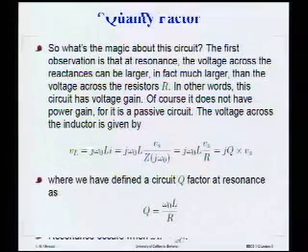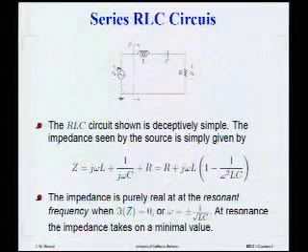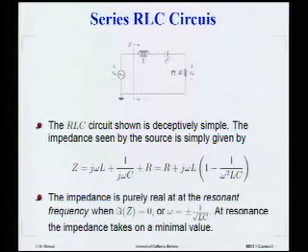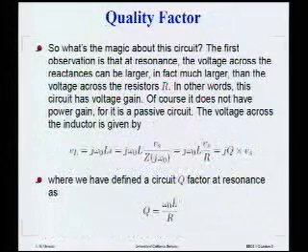So in this circuit, when current is flowing at resonance, the voltage Vs appears across R, right? But the voltage across this inductor and this capacitor can actually be quite a bit larger if the Q of the circuit is large. So imagine you put 1 volt here and you see 1 volt across the resistor, but you have a Q of 1,000 in your circuit. That means there's 1,000 volts across this inductor and 1,000 volts across this capacitor. Well, that's pretty exciting. We should be able to do something good with that. Okay? Questions or comments?